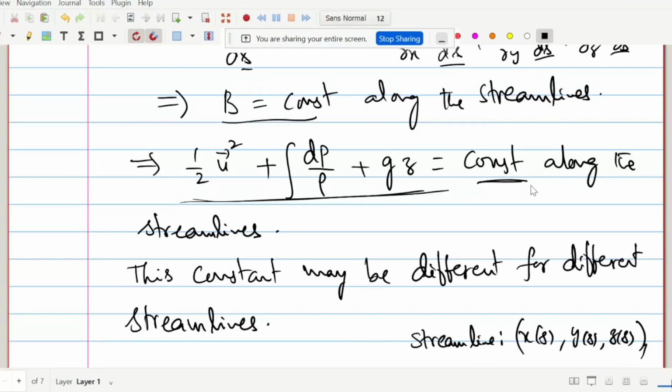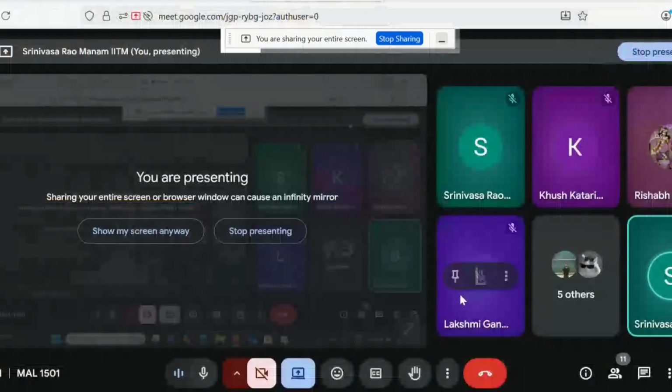Right now, what I'm trying to say is, for irrotational flow, how exactly does the integration of this momentum equation help to solve the problem? Instead of looking at the full water wave, full fluid problem where you have 4 PDEs and 4 unknowns, or 5 PDEs and 5 unknowns, instead of solving that general setup, if you assume certain irrotationality, then your equation becomes a linear equation. That is your Laplace equation. So we'll first show how the equation becomes your Laplace equation. Let me show you that first.